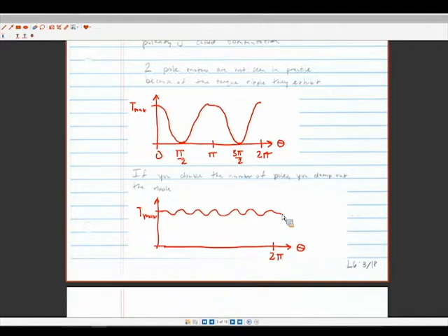This is really a disturbance to your system. If you have a control system, you're going to probably model to the mean of this torque in terms of the current torque relationship. But at some angles of rotation, you're going to get a little less than that. Some angles of rotation, you're going to get a little more than that. And that creates some inconsistencies in your motion, which will definitely reveal itself. And if you're looking at really high precision robotics, this becomes an issue. That's not really a topic for this class. That's more of an advanced topic. But I think everyone who's going to be an engineer and use motors should realize that with DC motors, you're going to get some sort of ripple behavior from it.